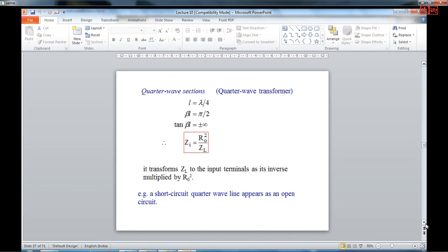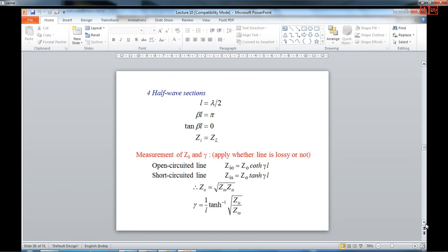other places also. Okay, so this is it. Then a half wave is also discussed. The half wave is going to be for an extension of the transmission line. If you want to connect a load in a particular system, and that load position where you want to add is inaccessible, we extend the line by half wavelength so that the currents and voltages are not disturbed and you can connect the load at that location. There is no disturbance electrically for the entire system. So half wave lines are used for repeating the load impedance values.